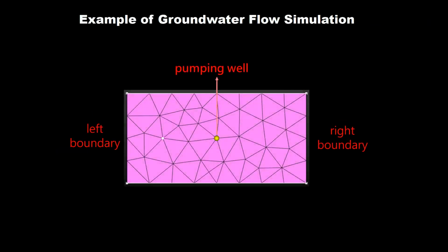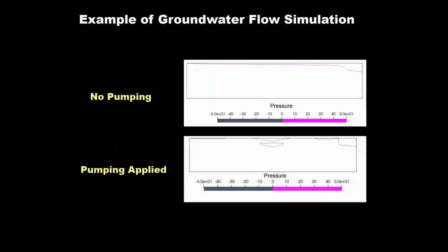This video demonstrates the simulation of three-dimensional water flow, featuring 2 measured water levels and 1 pumping well. Groundwater is continuously extracted at a constant rate from the center of the region. The simulation aims to assess how the groundwater level changes over time. The results will illustrate how the water flow, including its velocity and direction, changes throughout the simulation period.